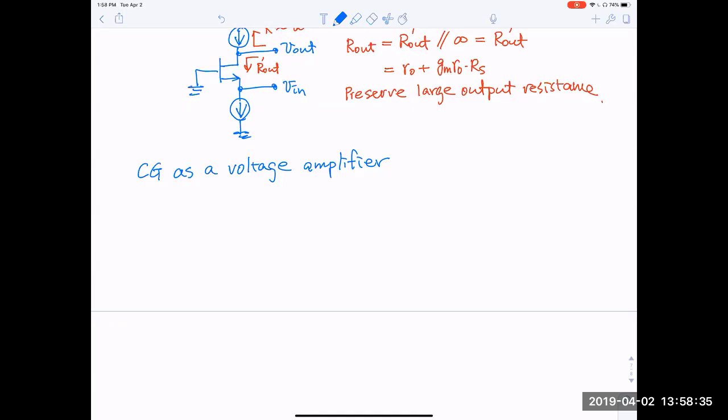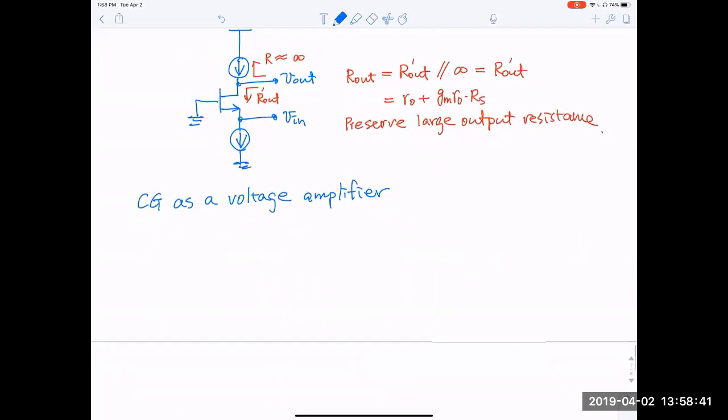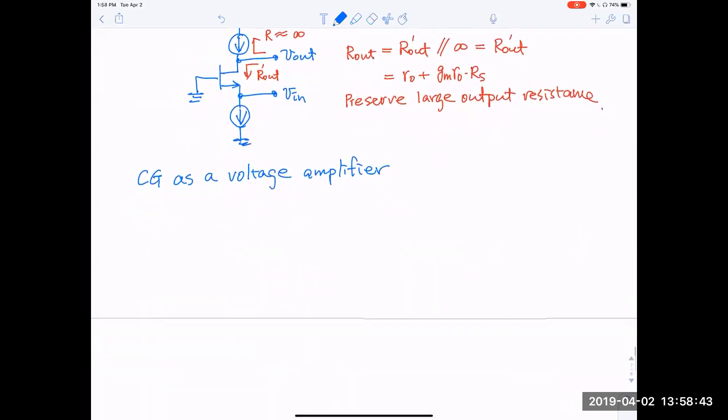And actually, this problem becomes very simple. We have already done the hard work of figuring out the two-port model. So we can basically just take the two-port model of a common gate. So it is input and R in is 1 over Gm, all right?